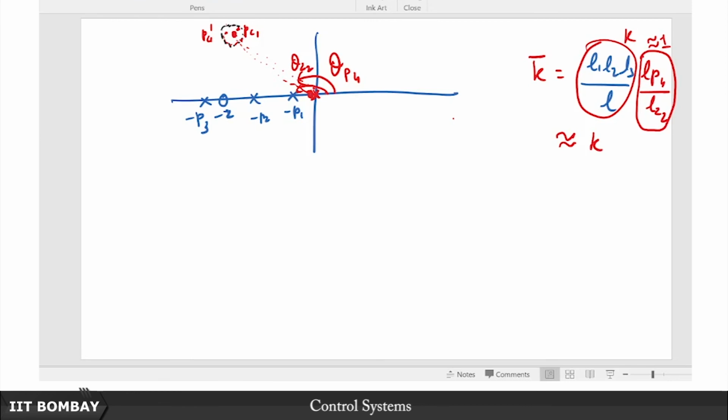But one caveat, you should never ever rest easy with such a design and feel that you have done your task until you carry out a simulation. Because remember, all of the derivation and everything that we did for the settling time and rise time and all these performance metrics, the percentage overshoot, were under the assumption that we are dealing with a second order system. But clearly here we know it is not a second order system. So where could the problems arise?